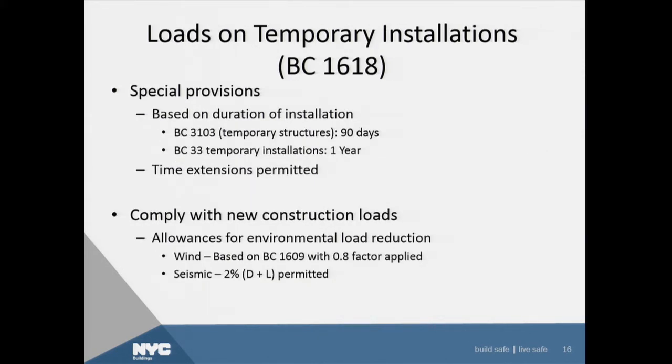A very significant change that was made by the code committee was the inclusion of loads on temporary structures and how to address them. This is something that we're probably one of the first jurisdictions to adopt, but we have provisions for structural design and loading requirements for these temporary structures used either during construction or temporary installations that are used as an alternate type of occupancy in some cases. So the provisions there are special. They're based on the duration of the installation.